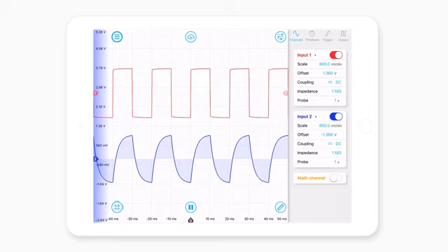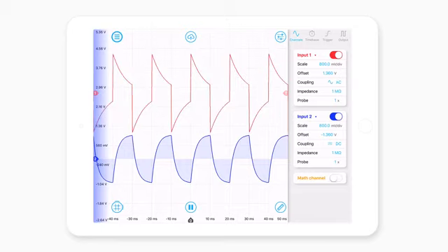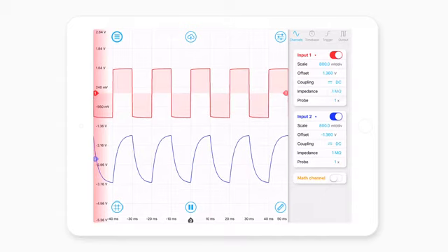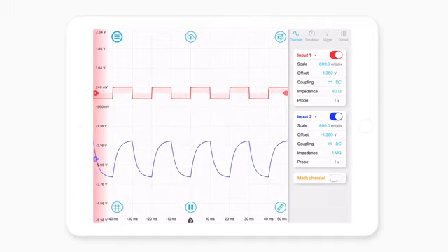The thing to note about coupling is that the corner of the AC coupling high pass filter is at about 90 hertz, which is why the red trace coming in on channel 1 here looks kind of weird. That's simply because it is a 50 hertz signal and it's being high pass filtered. So we'll go back to DC coupling, and the high impedance that we have is a 1 mega ohm load. That's very, very useful for characterizing signals using probes. But if you were instead analyzing an RF signal or an RF system with a nominal impedance of 50 ohms, then you could change that here.